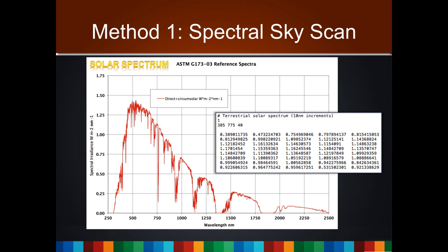We can derive a solar spectrum in whatever increments we want, and then we can just put it in a file and use the spec file type for the sun. It changes a little bit with the sky atmospheric conditions, so you could compute that correct solar spectrum. In my examples, I'm just using the same solar spectrum no matter what the sky is, unless there's no sun.